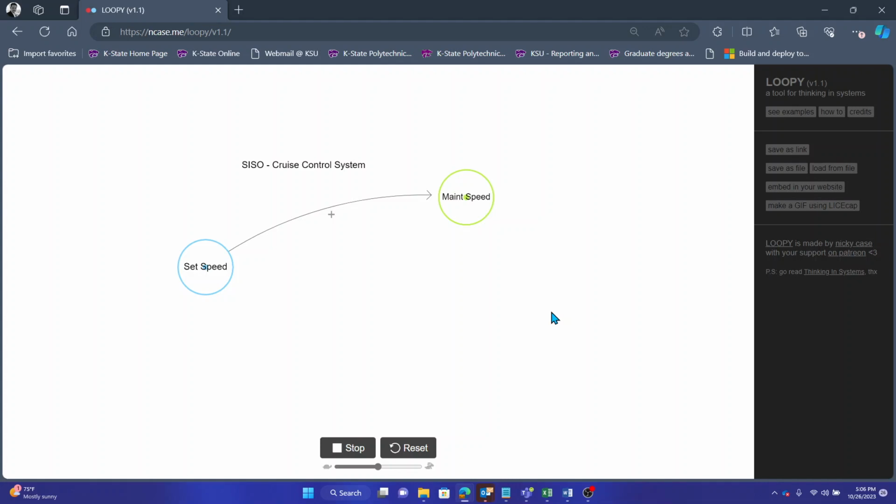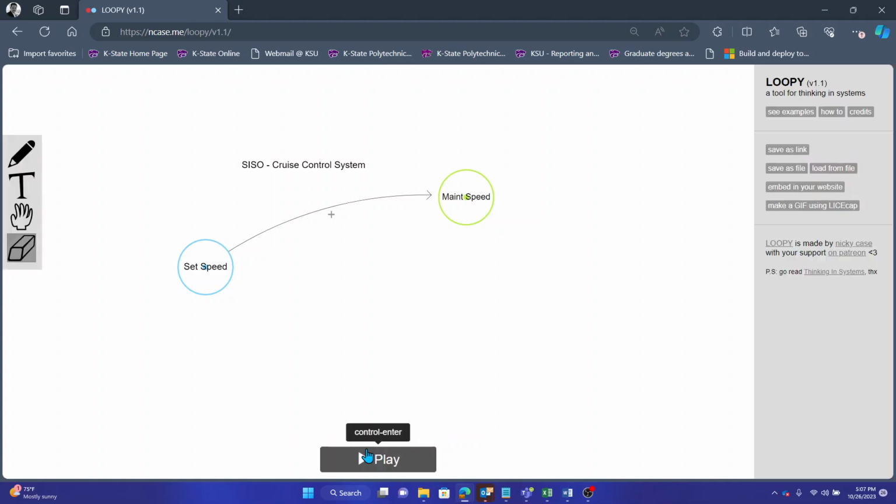I will use my normal cruise control system to maintain speed on inclines and declines, right? But then I'll also use radar systems to do a radar following with the car in front of me to maintain my speed, in addition to my normal cruise control, which means I have two inputs. I have my following distance between me and the car in front of me, as well as my ground speed. So there are new, more modern cruise control systems anyway. Where I'm going is they're more than just simple SISO systems. Okay, so I'm going to stop here. That's a SISO. So I said that I would do a SISO.